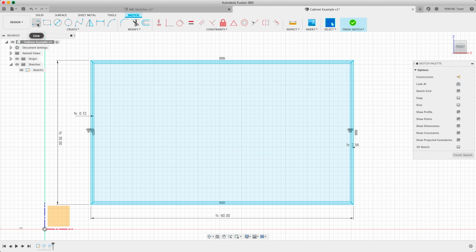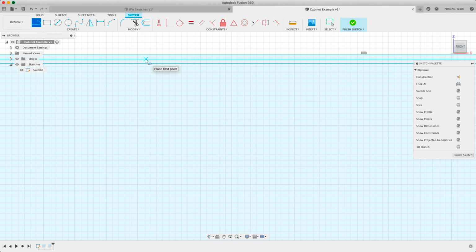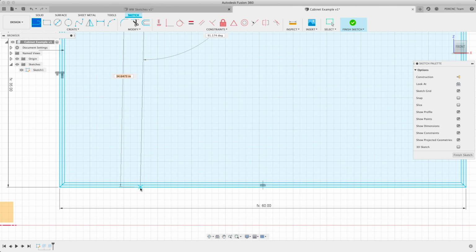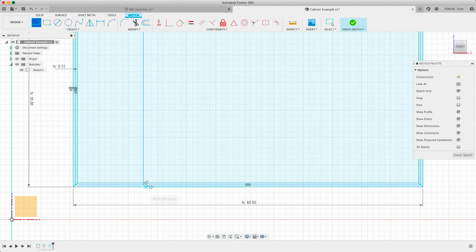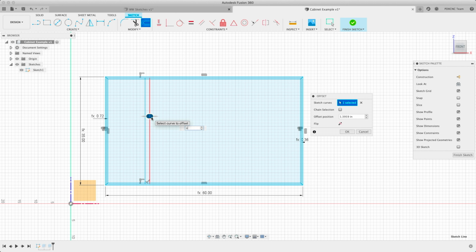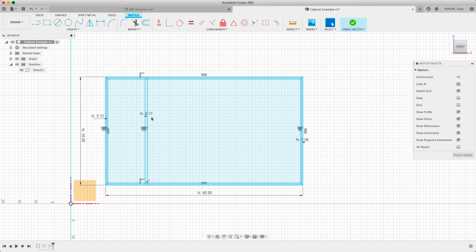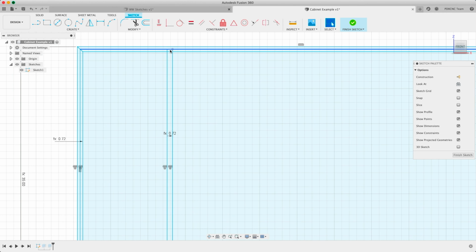I like to just click a line here. Select the inside line of the dado line, the halfway mark. Make sure it's straight all the way down. You see that perpendicular. So we've now drawn one. I'll do an offset with O. Type ply. Enter. So now we've got a divider that's exactly the same thickness as our plywood, and it has a dado depth.